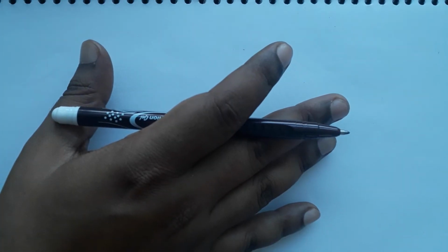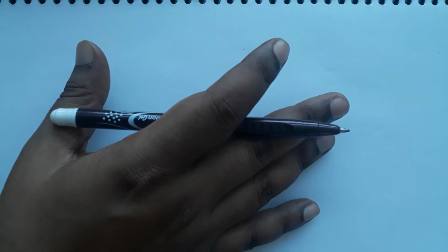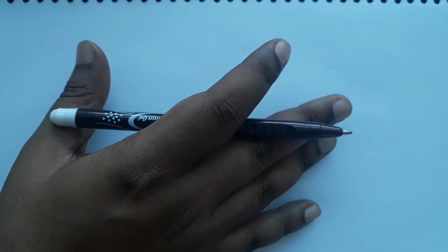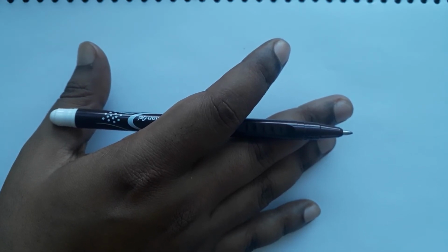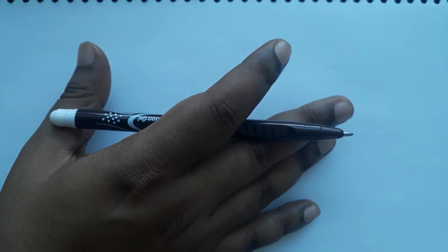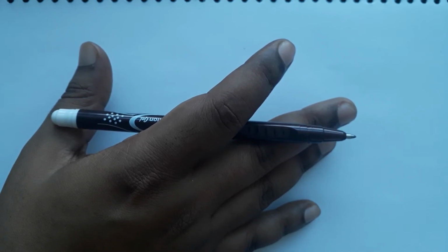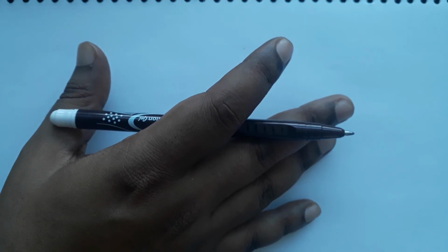Nevertheless, the point is that the material is not homogeneous at the microscopic level. So, even if you do not have any defect in the material, you will still have grain boundaries which will act as a defect. Even if you do not have grain boundaries, you will have dislocations, and those dislocations will be stopped at some point of time, and then they will not be movable. So, they will be sessile, and once that happens, the deformation starts getting stacked at that point of defect, and because of that the damage will increase.